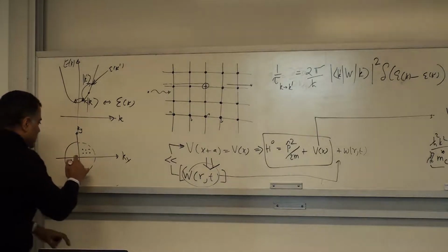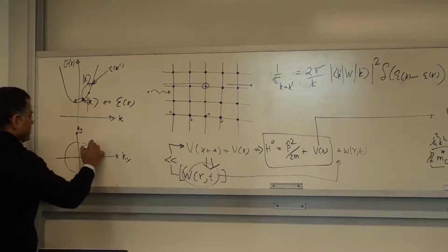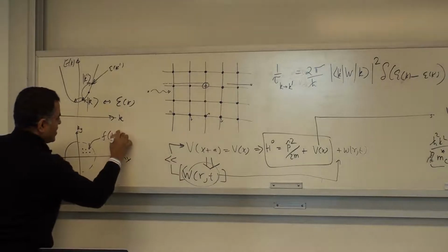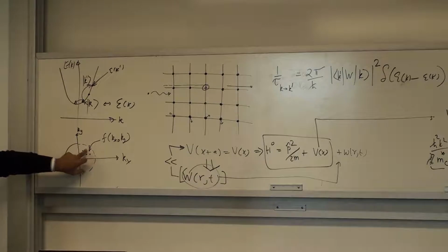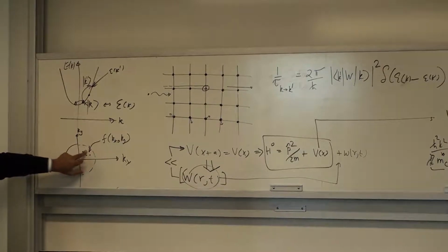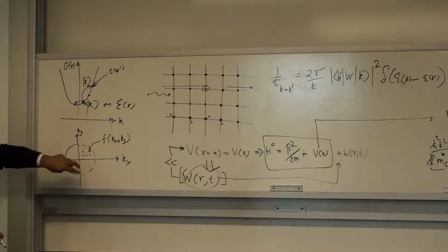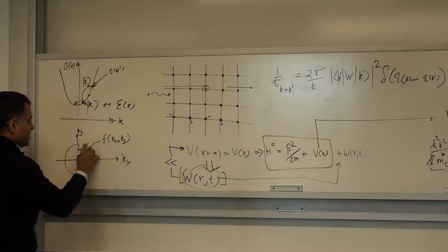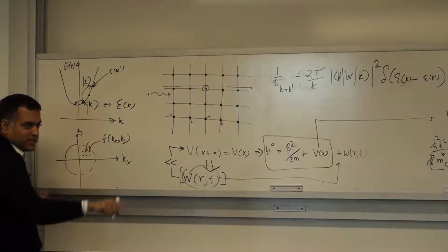So if I allow scattering, what we are trying to find out is... I had written down the kx, ky for the ballistic situation by just saying that the right-going carriers share the same Fermi level as the source, and the left-going carriers with the drain, and so that locks their Fermi levels. And once I put an electron inside any mode here, it stays in that mode till it gets out on the other side. Does that make sense? I mean, that's ballistic transport.